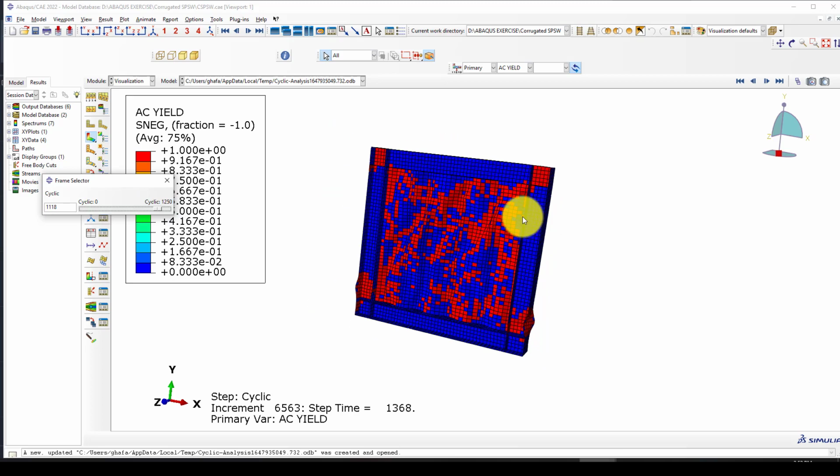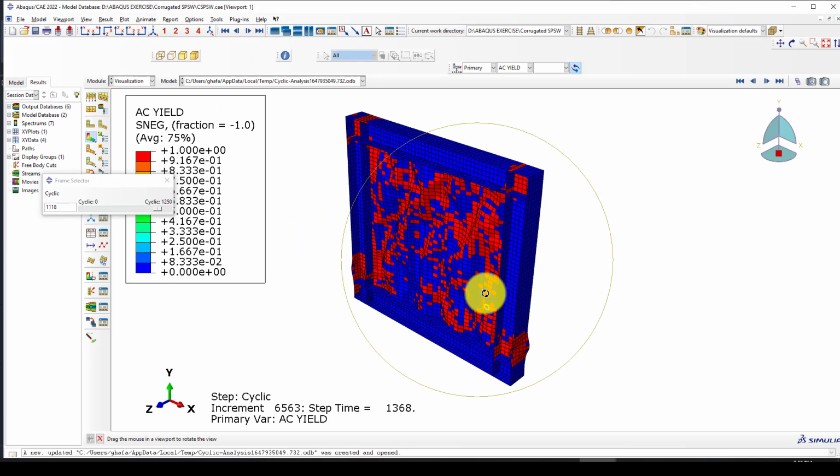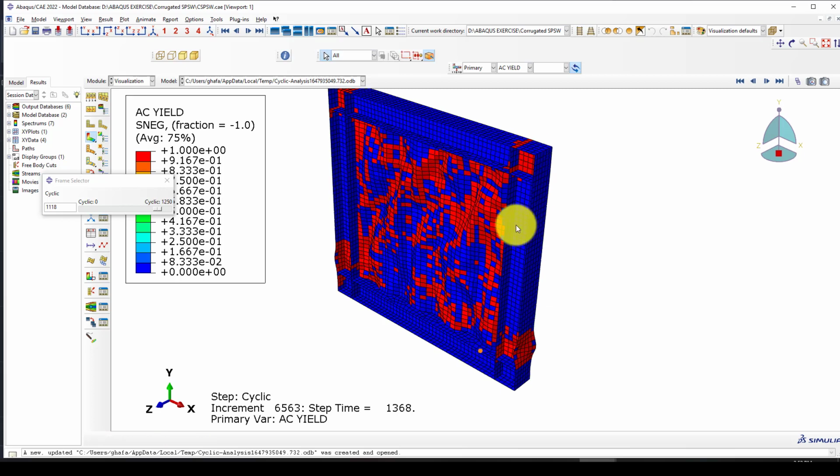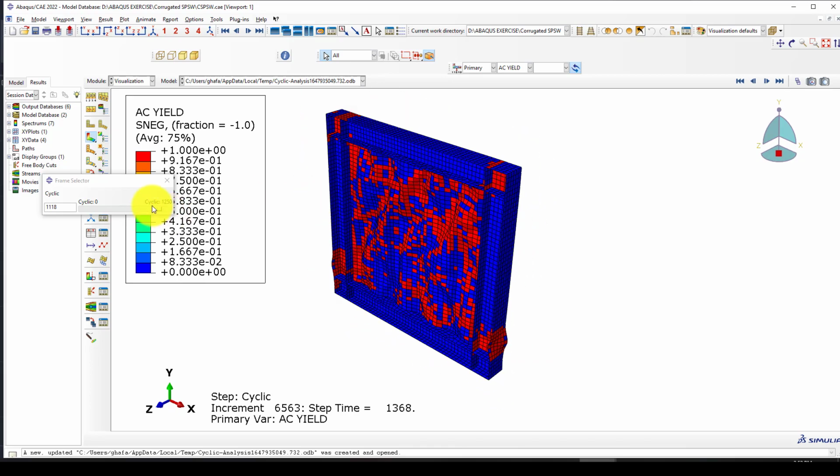One thing to note in a practical model or construction is that the column and beam shouldn't be the same. Mostly the column should be quite strong and the beam should be weak. So this is the principle of designing such kind of structure.